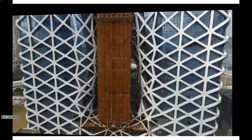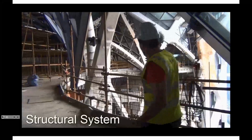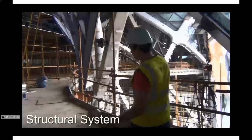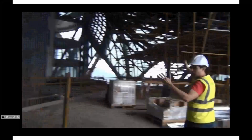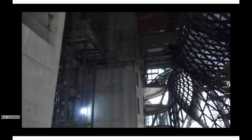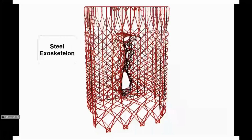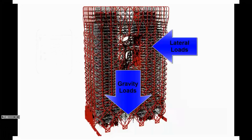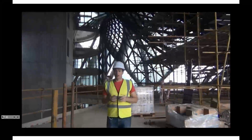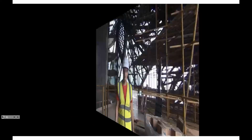So what is the structural system of Morpheus Tower? Well, as you can see here, we have a steel exoskeleton clad in aluminum. As you can see over here, this is the part of the 42-story atrium, surrounded on each side by a concrete core. Both the concrete core and the steel exoskeleton help support the building in the gravity and lateral cases. And because we're in a typhoon climate, that means that we can have severe forces running through this exoskeleton.